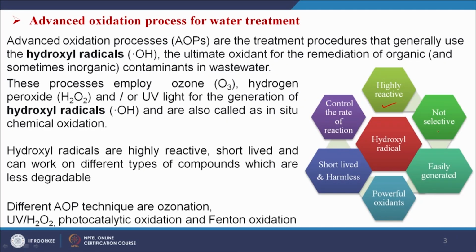Hydroxyl radicals are highly reactive, they are not selective, they can work on all types of molecules, organic, inorganic etc., and are easily generated, not so easily, but it is not that difficult either. And they are powerful oxidants, we will see that hydroxyl radical is a very powerful oxidant, and it is short lived and does not cause any harm for the application of the treated water, because these radicals are short lived.